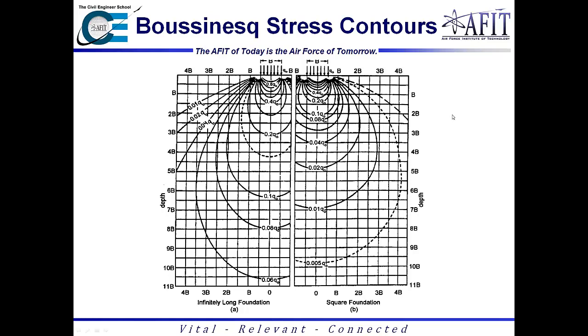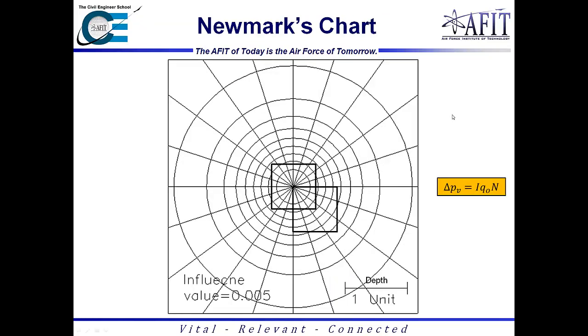There is one more method which you could potentially use on the morning exam. However, I think this would be more of an afternoon topic, but I just wanted to at least show it to you. So this is called Newmark's chart, which Newmark kind of took a lot of what WMSS did and then just kind of created his own chart for it, so you can create any sort of foundation on here. So you can deal with irregular shapes, circles, any type of foundation you may have, and plot it on here to figure out what kind of stresses will be below that foundation.